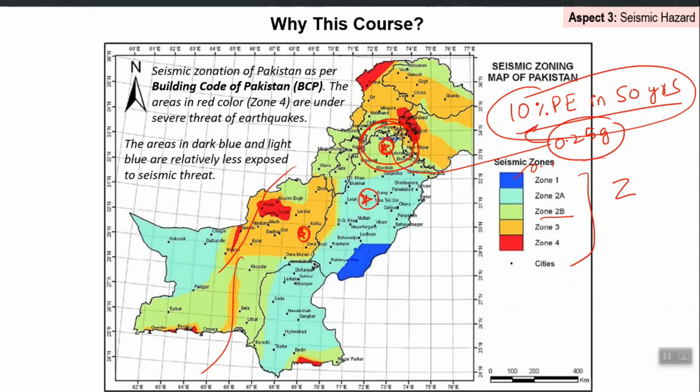But that 10% is kind of an acceptable chance, right? You may design for 2% probability of exceedance also, but correspondingly the PGA number will be far higher, and your design will be costly. Now as a PBD engineer, some developer can come and say that I don't want to follow the intention of the building code, I want to remain completely elastic, intact, even in a very rare earthquake, right?